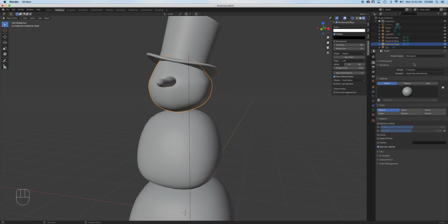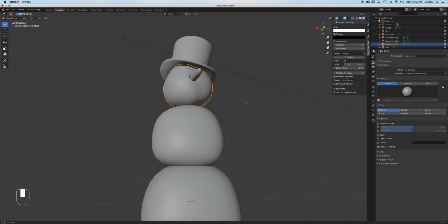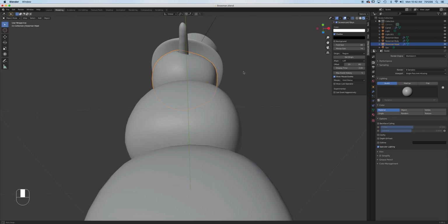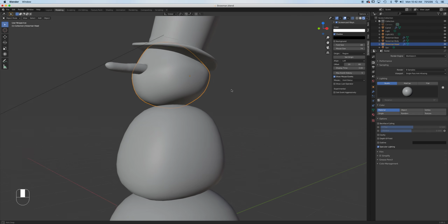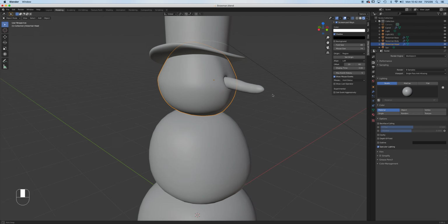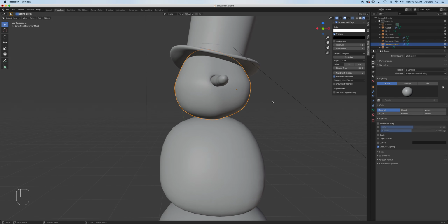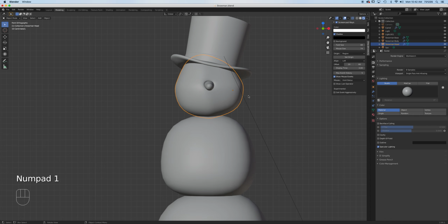Change EV to workbench. When working in workbench, you can see it's fairly smooth, and you can also see where your object might be needing to get smoothed out, like over here on some of the files. But it's quite all right at this point because you can't really see those once the material and lighting is in there. All right, so I'm going to go to the front viewport here, numpad 1.